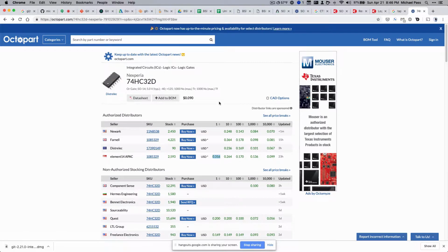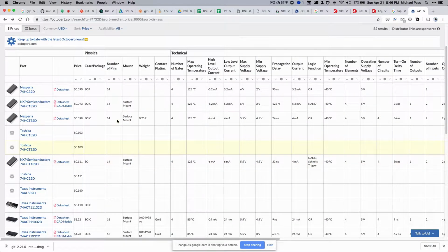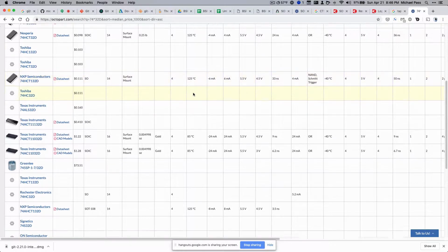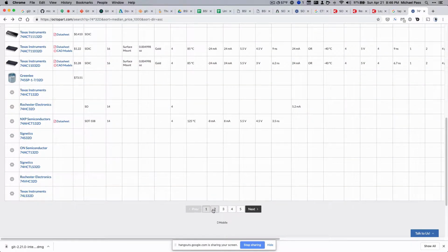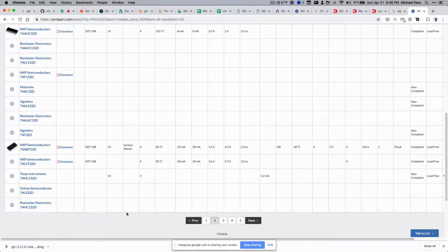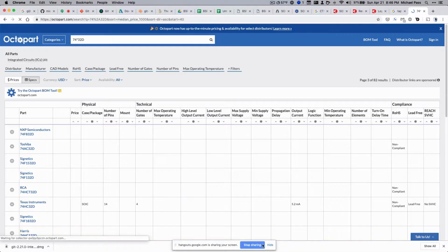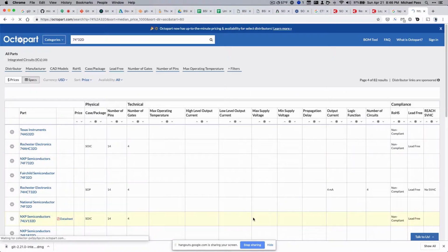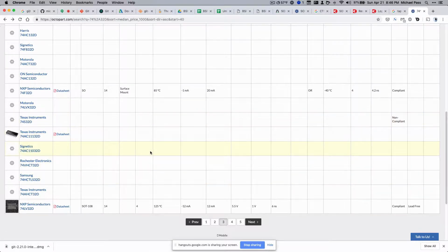So here, I mean, generally speaking, CMOS can go wherever TTL is. The reason I was looking at TTL was that they're hard to kill, but they require a regulated voltage level. So TTL is a better chip to get than CMOS. I think for us, however, in almost all circumstances, CMOS is better. We've got an automotive case, but then again, it might not be too bad if we have pull down resistors on everything. I don't know if it's that bad.